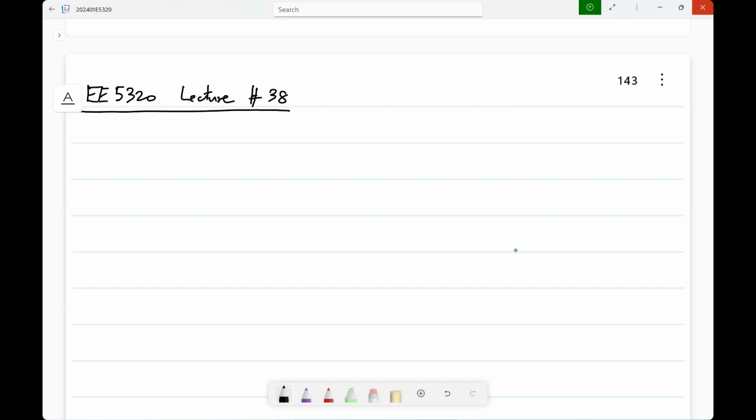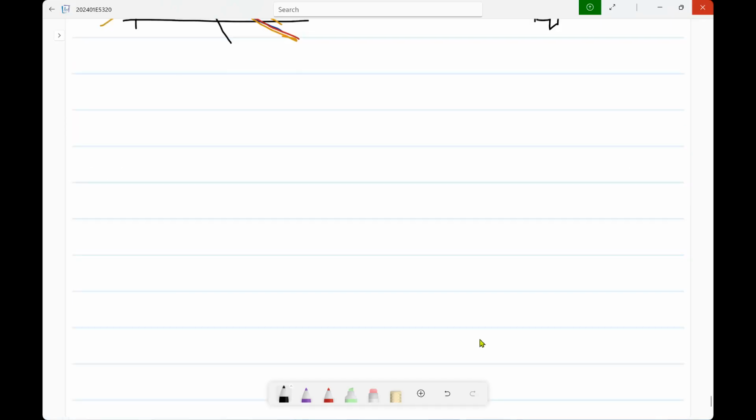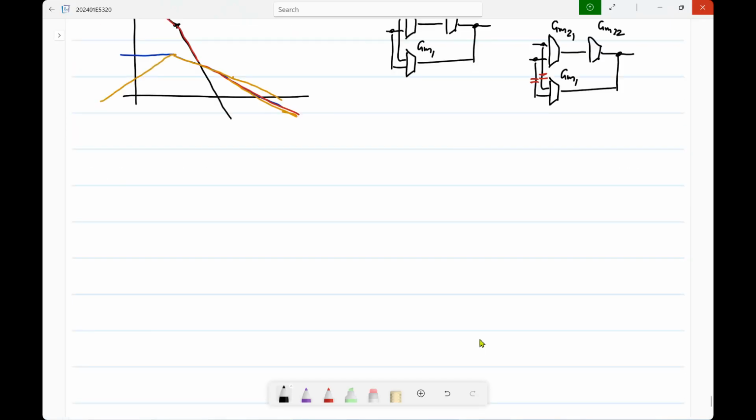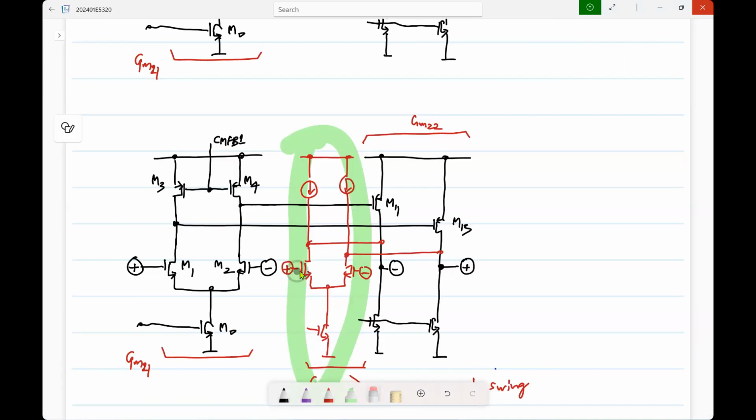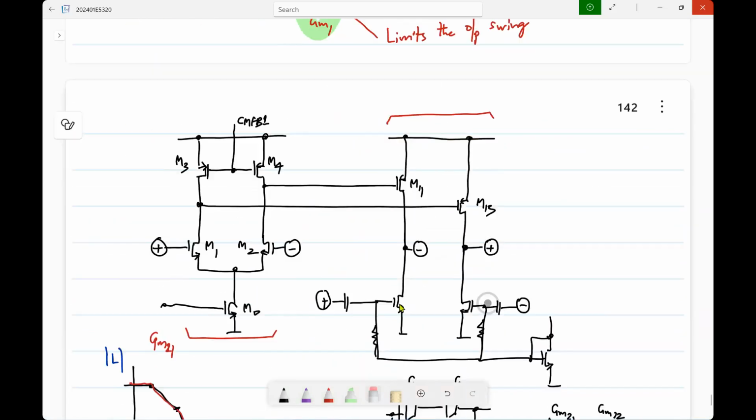If you implement it using a differential pair, you could compromise the swing limit, because then this stage could limit the swing, although the other stage is perfectly capable of giving a higher swing. So sometimes you can use this. The basic idea here is that the stage that connects directly from the input to the output, also called the feed-forward stage, is required only for higher frequencies, around the unity gain frequency.